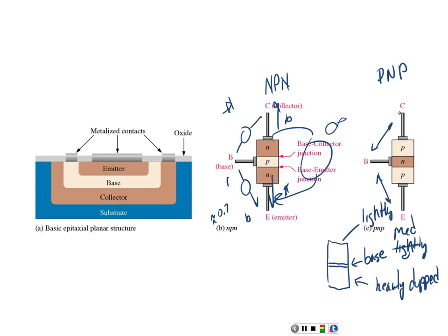So here, to forward bias this junction, I would have to put my red lead on the collector and my black lead on the base, and that way I would read, depending on what type of transistor it was. And then if I flip it around, it's going to read real high, right? You understand that? And if I read between the base and the collector, it's still going to measure real high if it's good. If it's bad, it might measure the same in both directions. So that's why you need to flip it around each time.